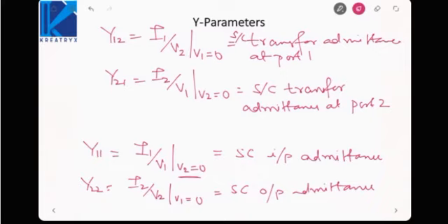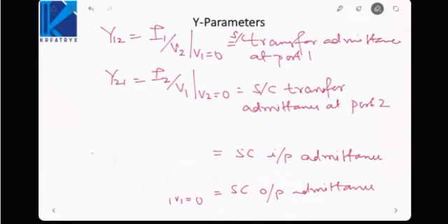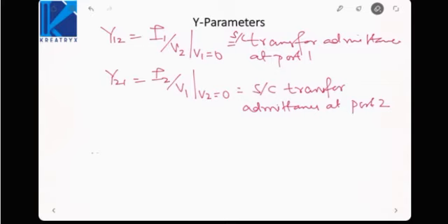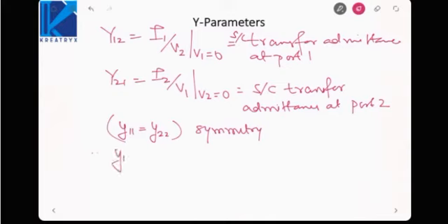So what will be the condition for symmetry and reciprocity here? It will be similar to the Z parameters. What I'll say is y11 equal to y22 for the case of symmetry. Driving point admittance must be same, and y12 should be equal to y21 for reciprocity, because again we must keep the ratio of excitation to response or response to excitation same at both the terminals.